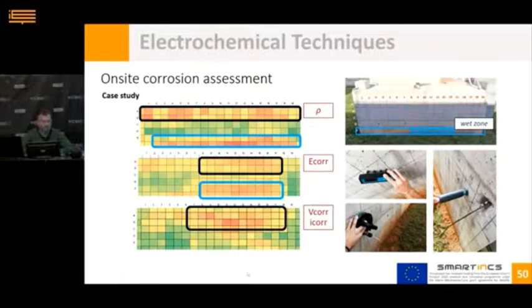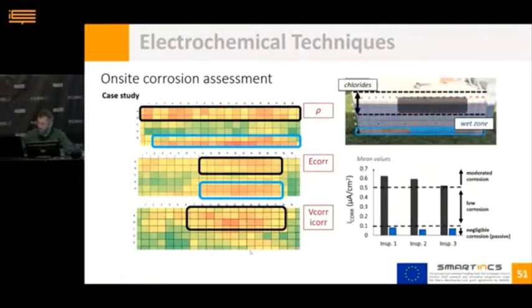Here there is no corrosion level high or similar. On the contrary, the upper part of the wall was chloride contaminated during concrete manufacturing. That's the reason why the upper part is the only one where a corrosion rate, in this case of moderate level, has been recorded.